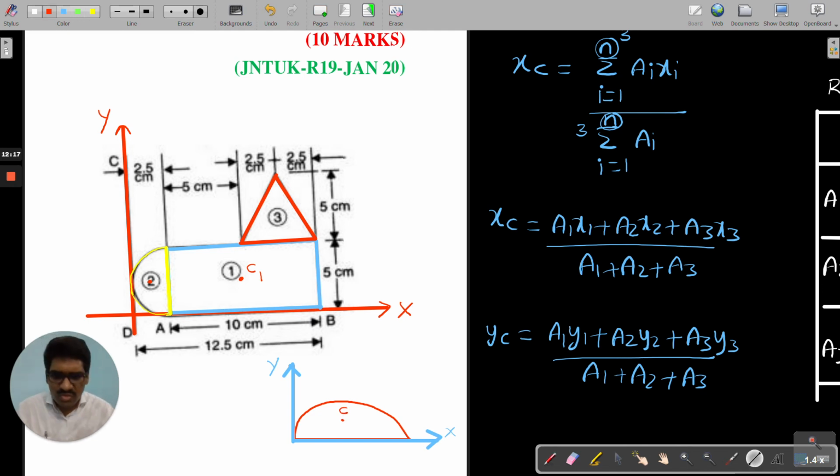Then what happens, this height will definitely be equal to how much? The value is 4r divided by 3 pi. This is the picture. But remember, all of you, many students get confused here. This is a diameter. From this diameter, the position of the centroid is 4r by 3 pi. But now this is my axis, and I need the distance from this one.